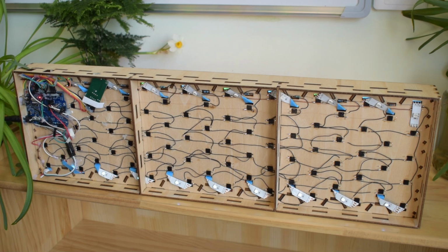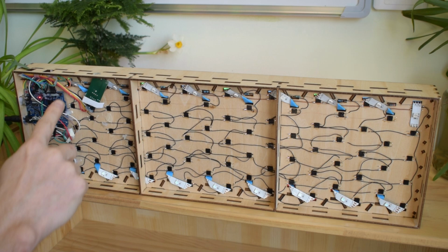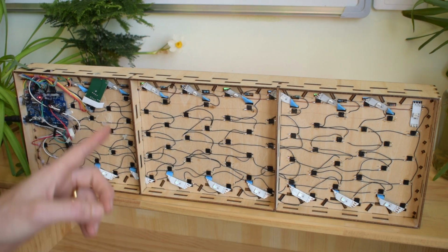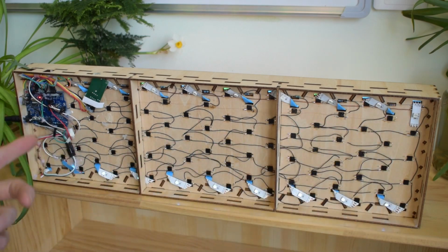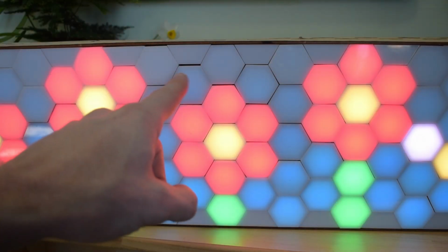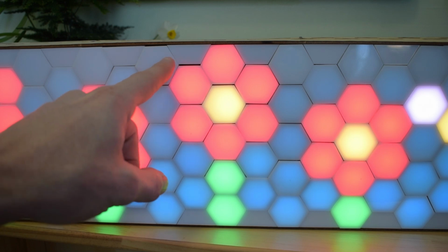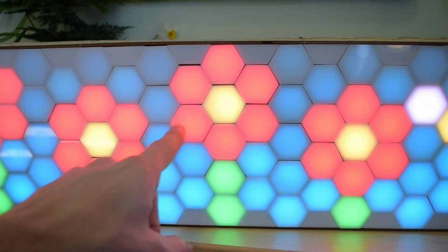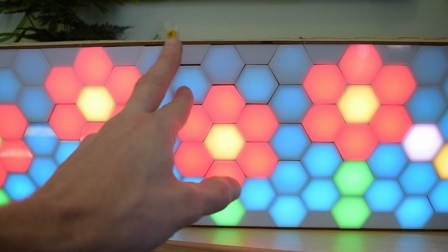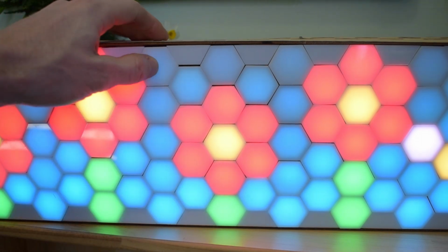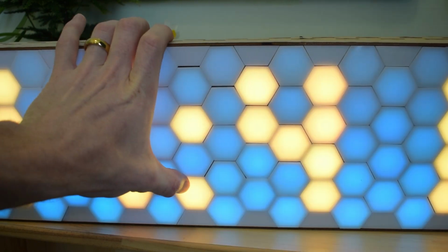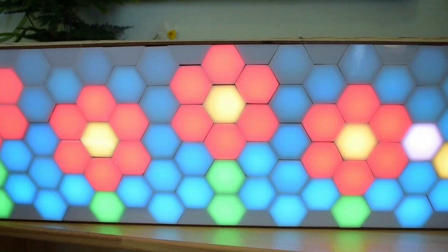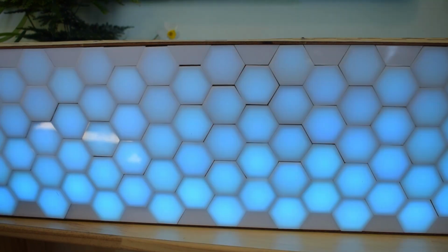The electronics are pretty basic, and the unique feature is I'm using just one row of resistors. The LED strip goes up and down, but I detect them in a zigzag pattern because they're all pulling off one single resistor to save components. And so I have to program it to figure out exactly where you're pressing on the screen.